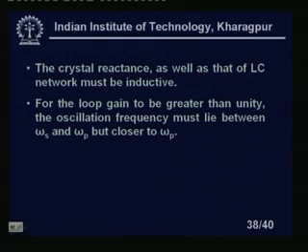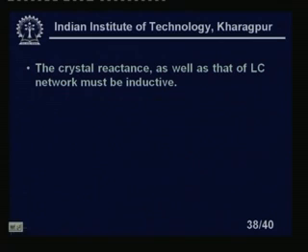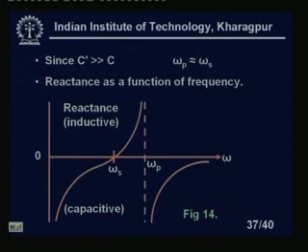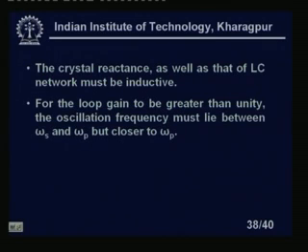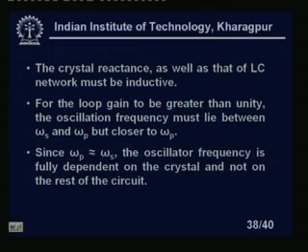For the loop gain to be greater than unity, the oscillation frequency must lie between omega s and omega p, but closer to omega p. If it is so, no problem, I can purposefully choose that.